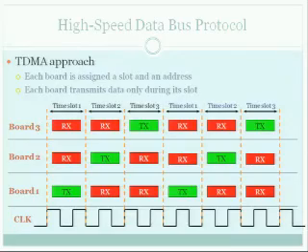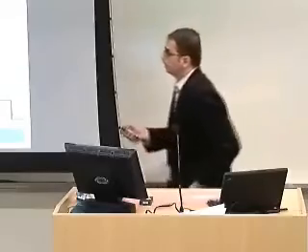Now, in the second case, in the case of the bus management, our main goal was to create some fairness in terms of using the communication channel. When multiple communicating pairs wanted to exchange information, we wanted to be able to support that. And given this design guideline, what we decided to do was to use a TDMA-based approach. Basically, every board, every CPLD in the stack is assigned a unique address and a unique slot.